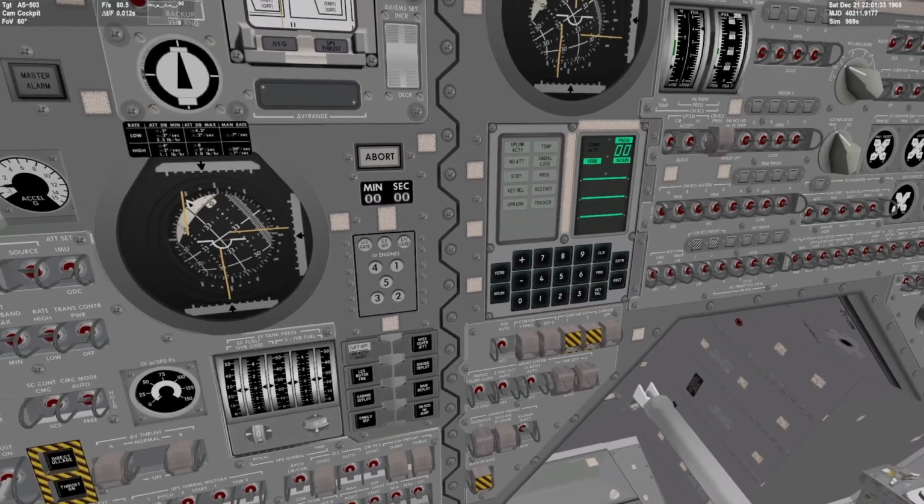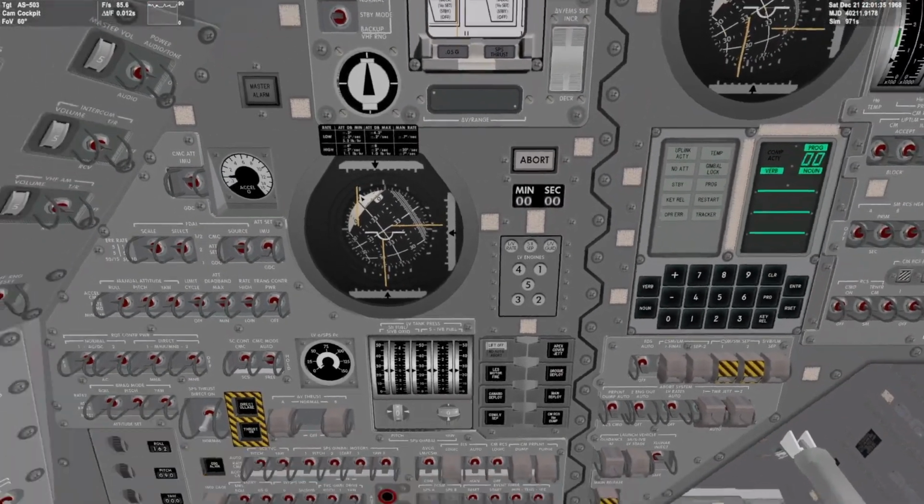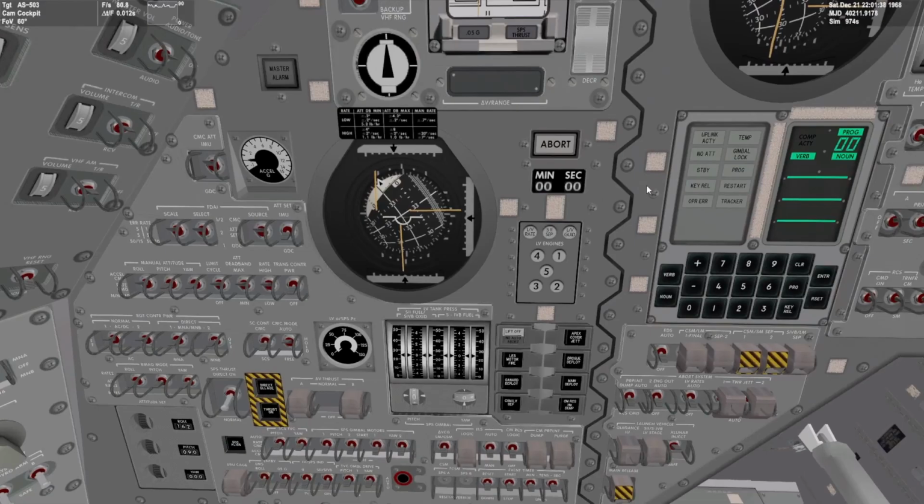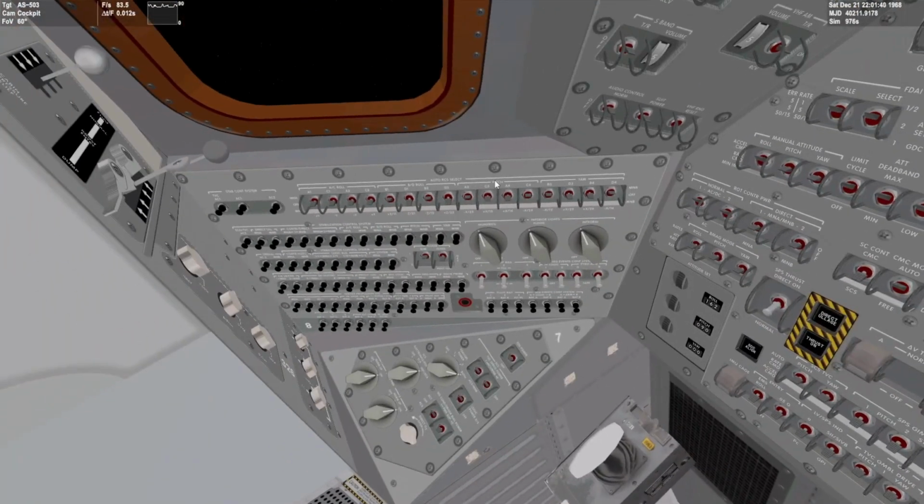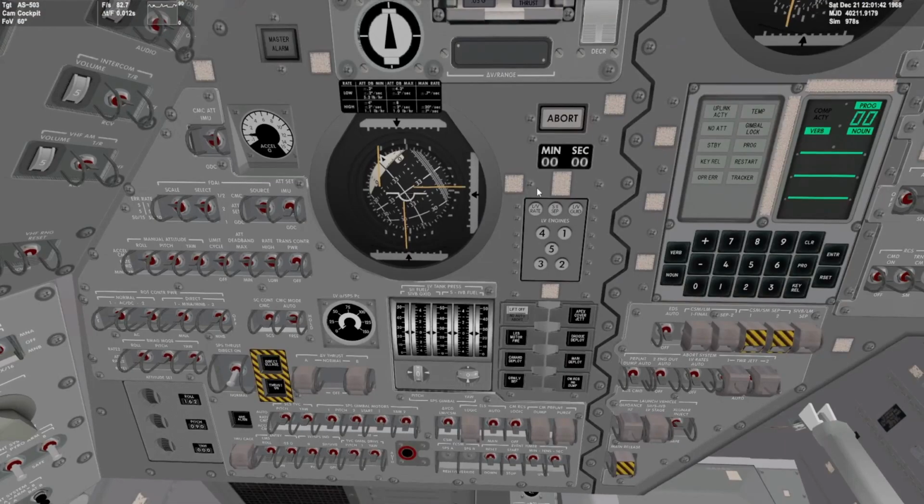And that's PTC. Generally, it just matters to maneuver to the correct position, update the DAP, configure your thrusters, and then switch the roll to accel command, and then just kick the spacecraft into a left or right roll at a very slow rate. Very slow in this case, probably closer to about 0.2 of a degree per second, but that's totally fine.